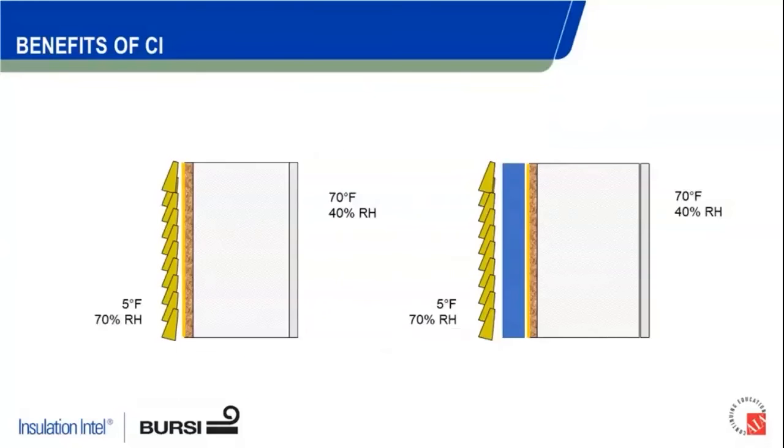And that's really some of the impetus and thought decisions behind Energy Code, why they're asking for this material, because it is much more efficient in that exterior portion of a wall system than it is in the stud cavity. So we're going to look at a couple other additional benefits of continuous insulation, in addition to, of course, the thermal numbers that we just ran through and examples you saw there. In this case, related to condensation control and the temperature vapor profile of a wall system.